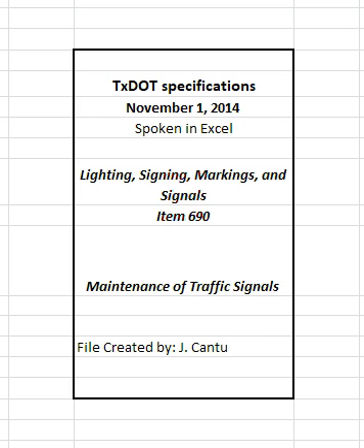4.20 Protection of utilities. Locate and protect all public lines and utility customer service lines in the work area. Notify the utility company and locate and mark, uncover, or otherwise protect all such lines in the construction area. Obtain information on the location and grade of water, sewer, gas, telephone, electric lines, and other utilities in the work area from the utility company.